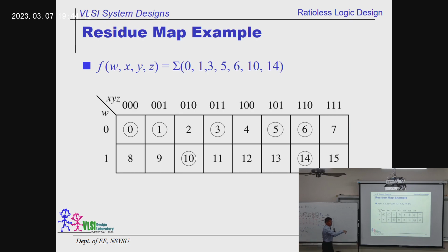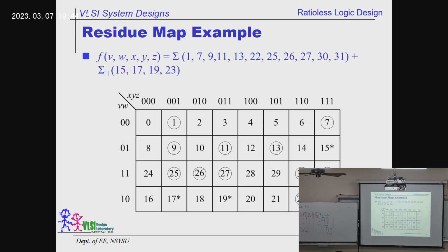However, this textbook uses a different approach, and it's more efficient. The idea is the same. Basically, it's a multiplexer idea. Before we go to the circuit design, we can see a different decomposition approach. See, this is a very big one. 5 variables, very big, and all students hate it. We have the summation of minterms. Then these are don't cares.